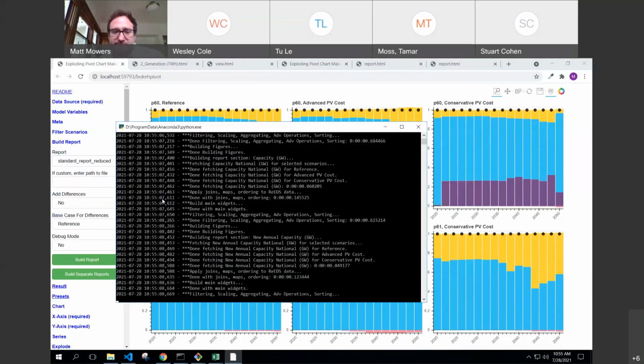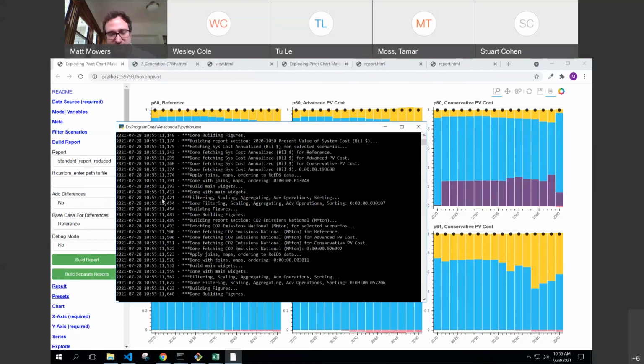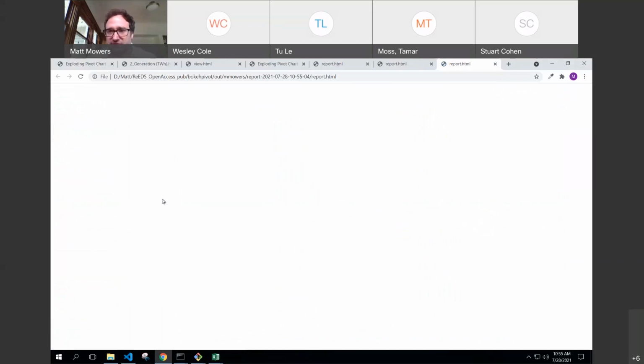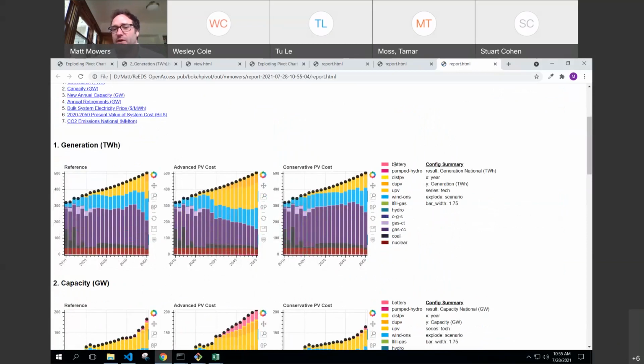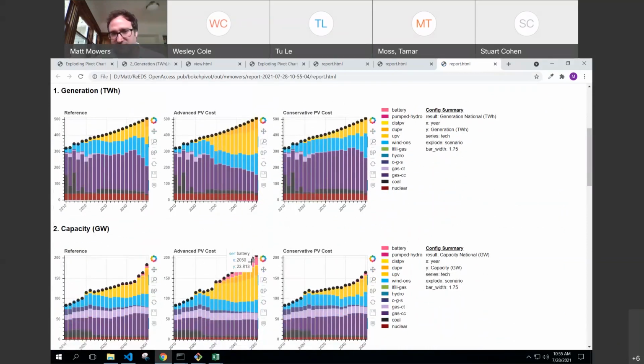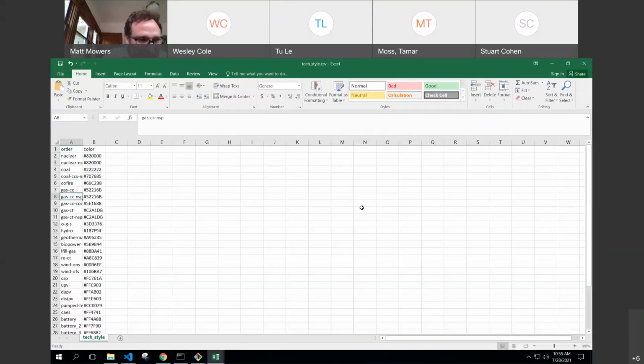Now the batteries should no longer be separated into the different hours. Those numbers were the hours of storage. But with this mapping file change, I can now have battery be just one entry here. So the capacity, yeah, this is just the full battery capacity. So that's how to do remapping. And then the styling here says for each of these display names, this is the color. So you can use a different hex color if you want to style them differently.